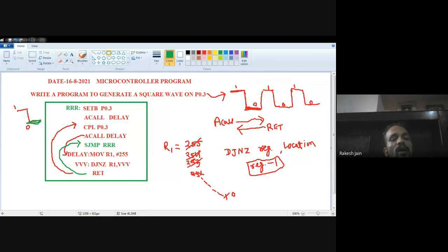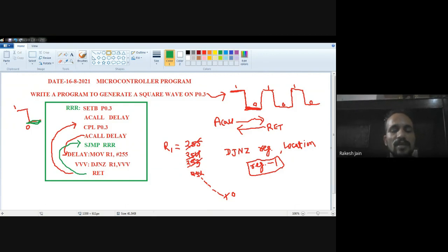Okay, very good. Now in the case of a microcontroller, we should use Keil software to convert this assembly language program. This is an assembly language program, but microprocessors and microcontrollers are devices which actually run on the binary values 1 and 0. Because we have to do the programming on a computer system via Keil software, it will understand the hex code value generated in hexadecimal format. So to convert this assembly language into the required hex file format, the hex file can be generated with the help of Keil software. So how to use the Keil software?